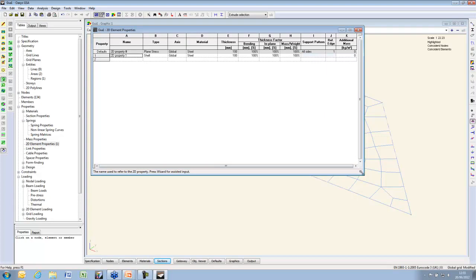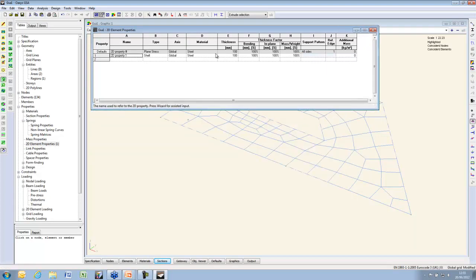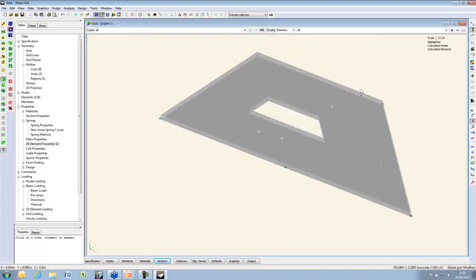In this particular case, I defined these as 100mm steel plate, or let's say 150 concrete. So in this case, these would represent solid surface elements, which we can then apply load to.